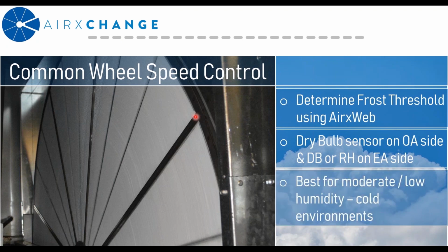Now, because bypassing air follows a more traditional performance path, it's a little bit easier to use in more applications. So it can often be used more reliably than wheel speed control in applications where relative humidities will be higher or start to rise. Therefore, kind of as a rule of thumb, bypass I see used a lot in moderate to low humidity spaces and moderate to colder environments. Typical building spaces that I see it being used would be universities, schools, research buildings, and gymnasiums.